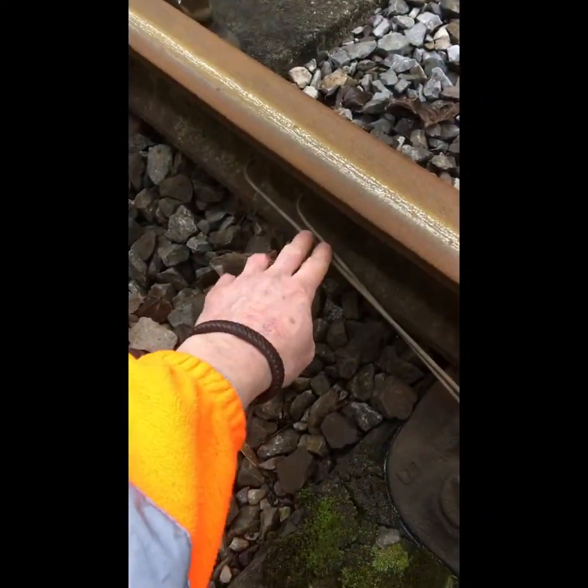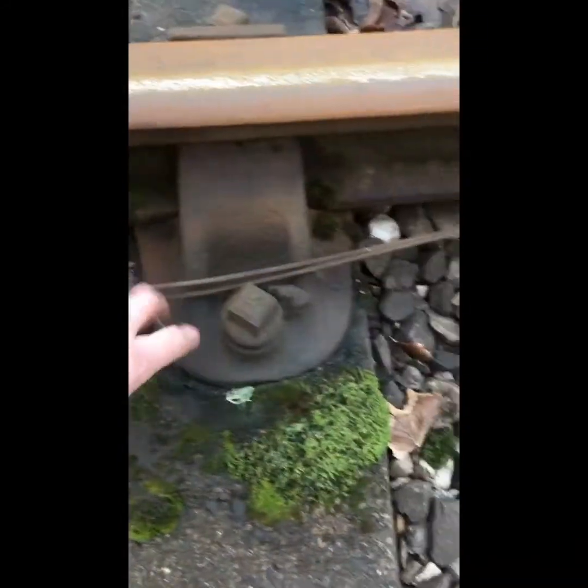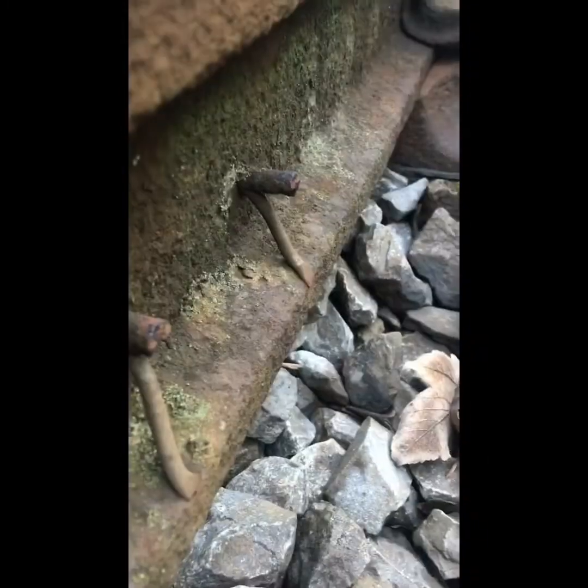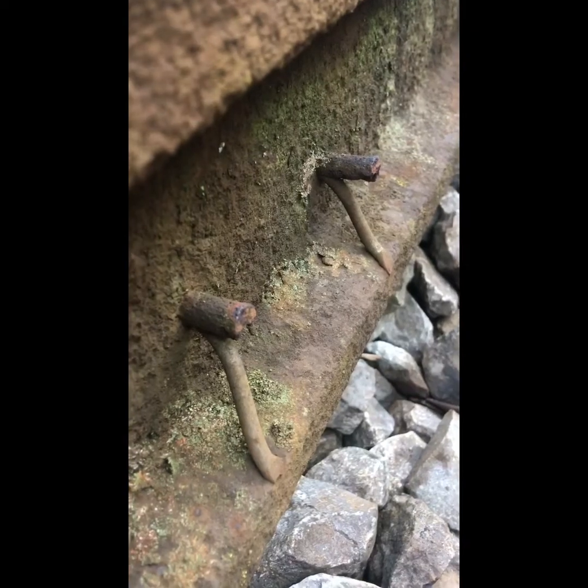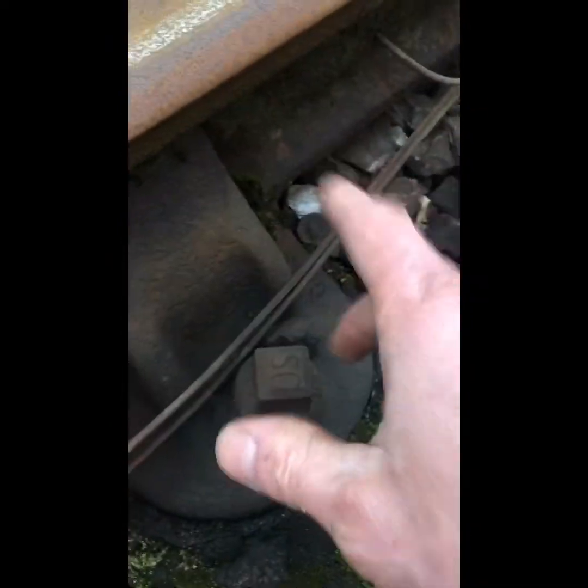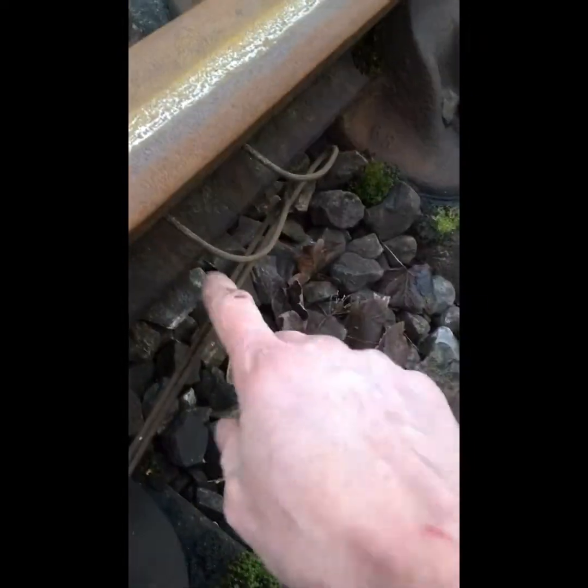So as S&T, we have our bonding wires which go through. These are doubled up. Some railways just single bond them, some railways double bond them, some railways triple bond them. Depends on your maintenance regime, and they're simply held in at the back by some tapered pins, and they hammer in quite easy and just hold the circuit as one. What you tend to do with your wires is have this nice bend back on, because obviously, as you can appreciate, rails expand. PUA want to come down, move things out the way, put spanners on, etc. So you want that little bit of movement in it. So we put that kind of expansion in there just for the sake of it.